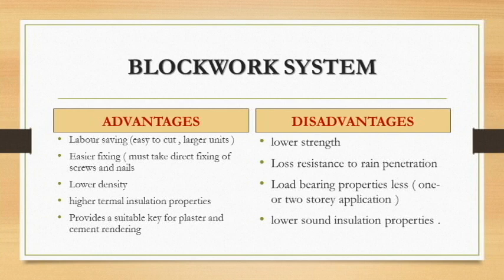The advantages of the blockwork system are labor saving, since the larger units are easy to cut, and easier fixing by direct fixing of screws and nails. There is also lower density, higher thermal insulation properties, and it provides a suitable key for plaster and cement rendering.